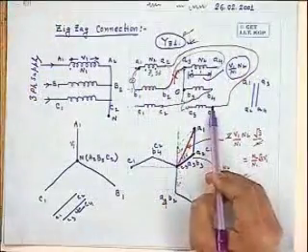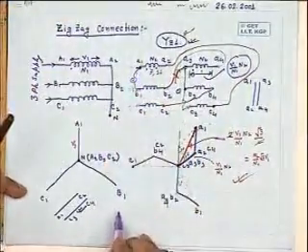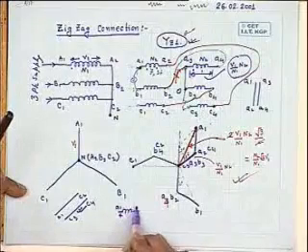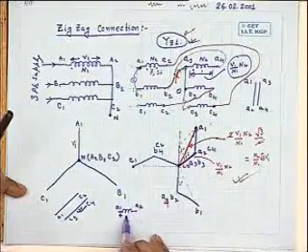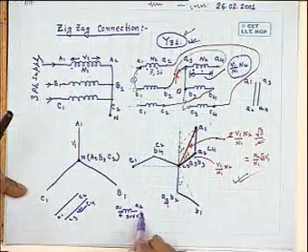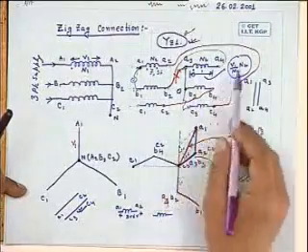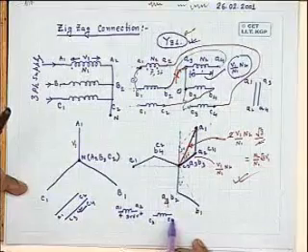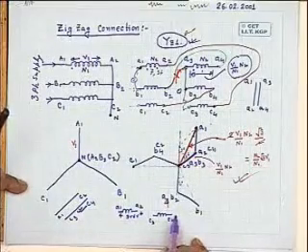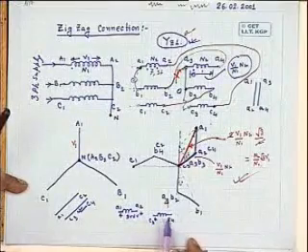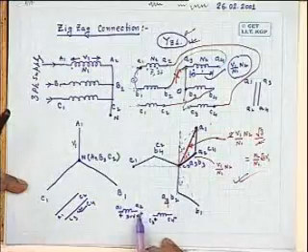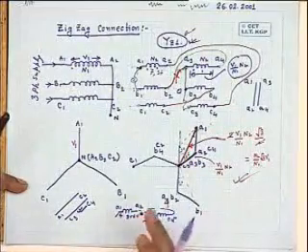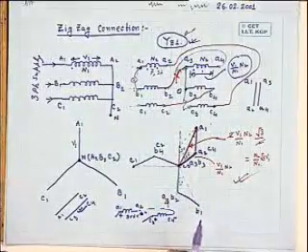The polarity is okay, yes, they are opposite. But you see the connection, A2 is connected with what? C4. See, A1 terminal with this A1, third harmonic voltage I will only draw. Suppose at any time A1 is positive, and this is A2. This is third harmonic voltage, with this plus, this minus. Now, what is the other winding connected? C4, C3. So this will also be cophasal. Which one will be plus, minus? C3 is plus and this is minus. And this is plus, minus. So these are connected. So the resultant third harmonic voltage available between these two will cancel off.